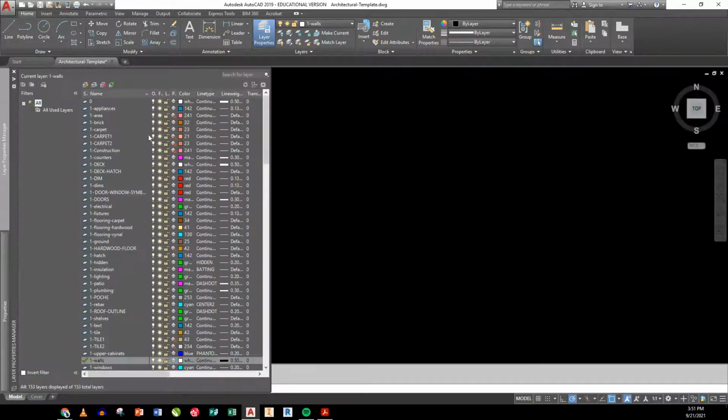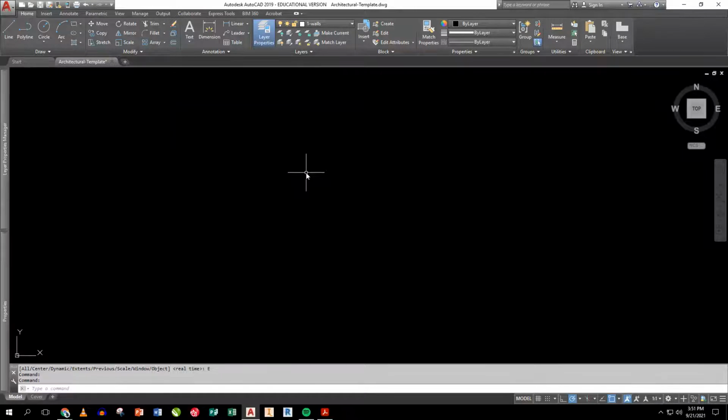And so that way, if I ever see that, I know those are construction lines. They won't print because they're set up in my print manager over here on my layer controls as no print layers. See, these are all non-printables. Okay. I can turn them on if I want, but right now, whatever.